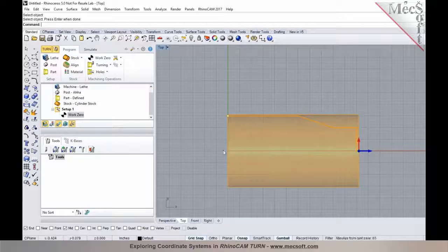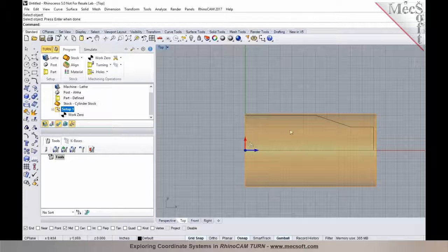But when you design the part and orient it, you need to make sure it's established at the backmost face in here. Now this would be similar also in SolidWorks. We'll talk about how, when we import a file and it's in a different orientation, we can easily orient the coordinate system for turning. So it's important to make sure that the back face of the part is at the origin.